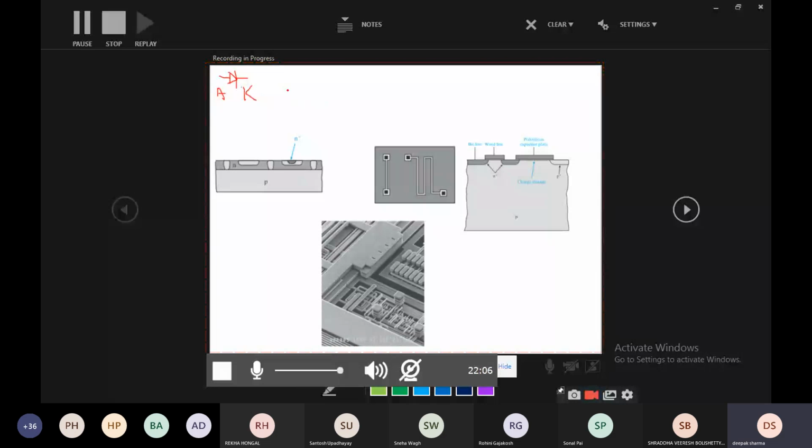So we will not bring the diode. We will not bring the diode, right? Why? Because all the fabrication steps have to be repeated. They have to be followed for the transistor, right? And after the transistor, if you want a diode, again mostly all of the steps have to be followed for fabrication of the diode also, right? So there will be unnecessary repetition of the steps.